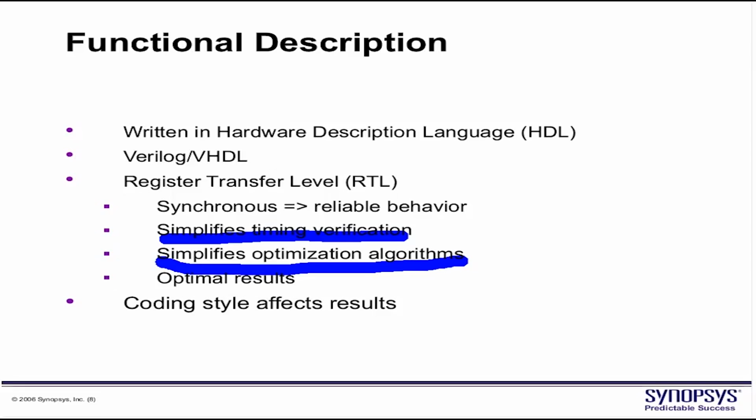Optimal results: it is very easy to set goals for a synchronous design as compared to an asynchronous design. Asynchronous design is very difficult to verify and to meet timing. So it is recommended that whatever design problem we have, we try to solve it in the synchronous domain, so that goal setting and optimization would be easier.